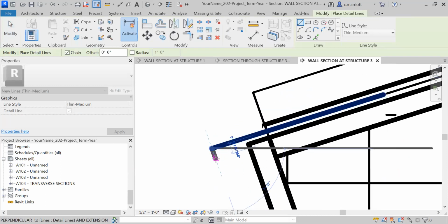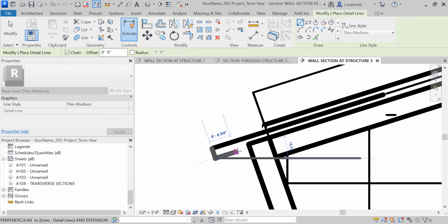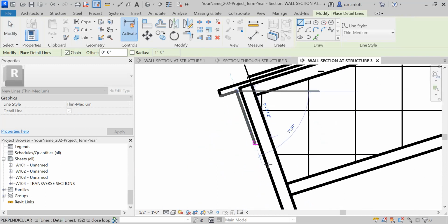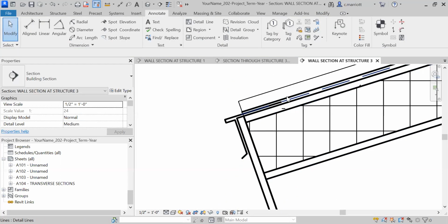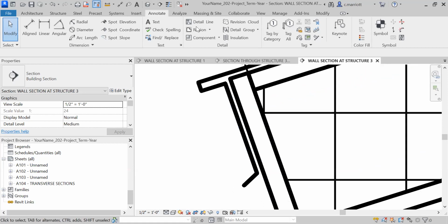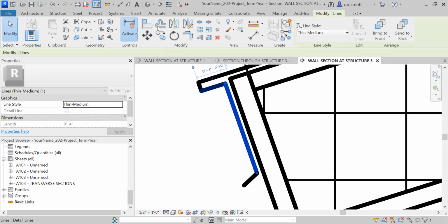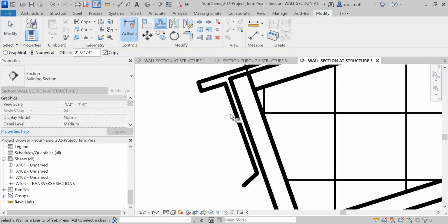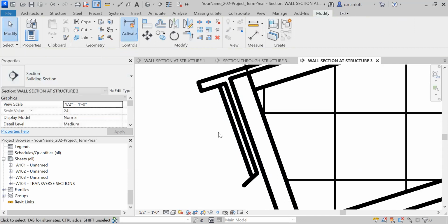So remember, the drip edge is basically just to keep water from backing up into the roof. I'll make this about 4 inches and angle it off like so. Okay, so the water will just fall into the gutter that we're going to construct next. Now let's move this line over a little bit, or let's offset a line. So we'll have one for the gutter and one for this. So I've got it set at 1/4 of an inch. Let's bring this over, and then let's go ahead and fillet